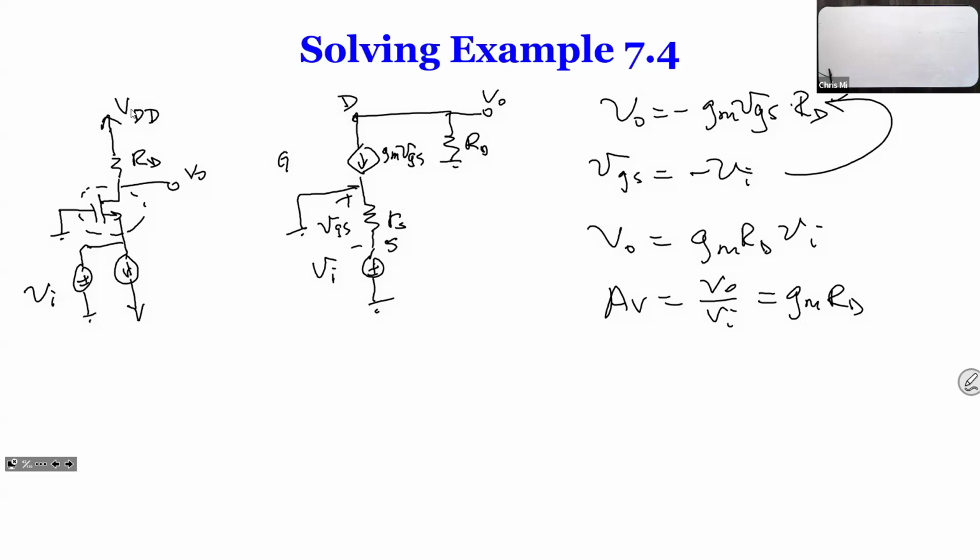Treat all DC current sources as open. If it's an AC source, of course, it's not open. When we're talking about small signal, we're talking only about the AC component. So we're taking a superposition of only the AC components. In superposition, all current sources become open and all voltage sources become wires. Okay, so this is what we get.